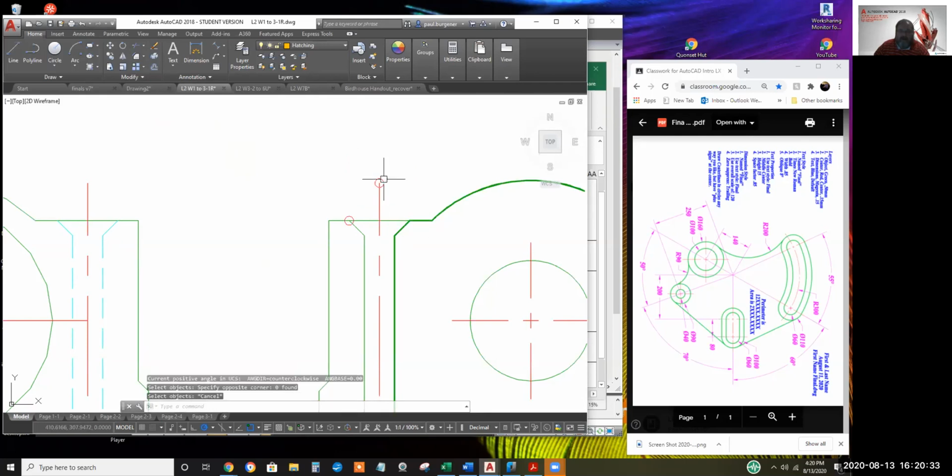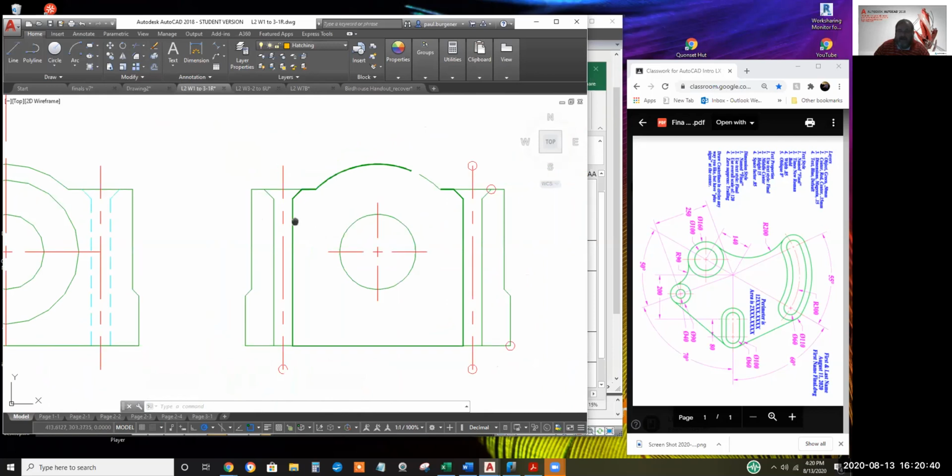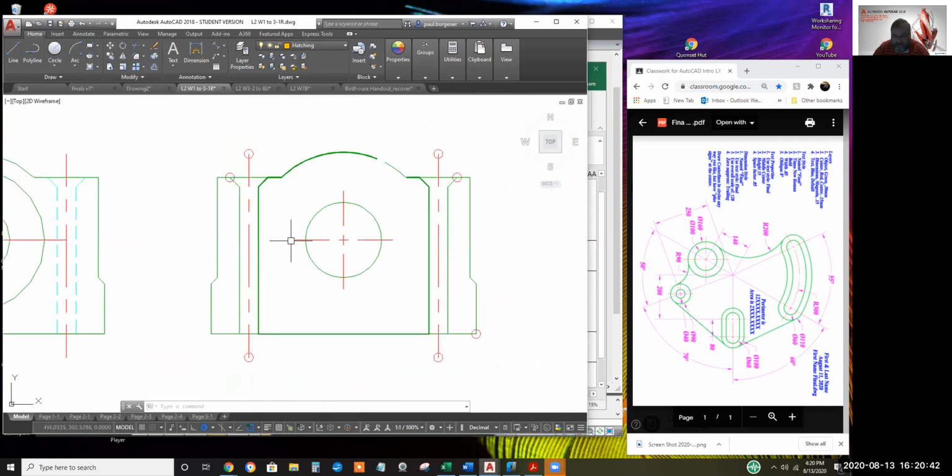So that tells me it's a glitch with the display, like the octagons when you zoom in fast on a circle. I'm going to regen, and I think they'll disappear. So it doesn't answer what they are, but it gets rid of them. Okay, thank you. My pleasure.